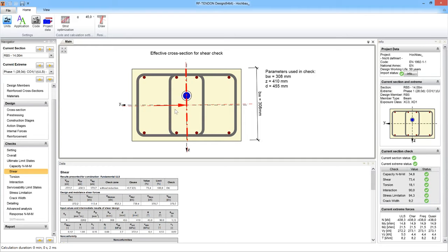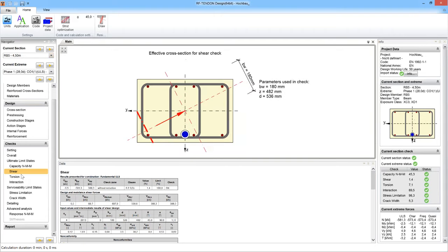If we apply a high normal force of pre-stressing, then of course just behind the anchor we should not use the sectional analysis. It is the anchorage zone, but I don't think I made it immediately after the anchor, and still RFEM integrates quite significant forces, but we can design them with no problem. So let's go back to the mid-span.